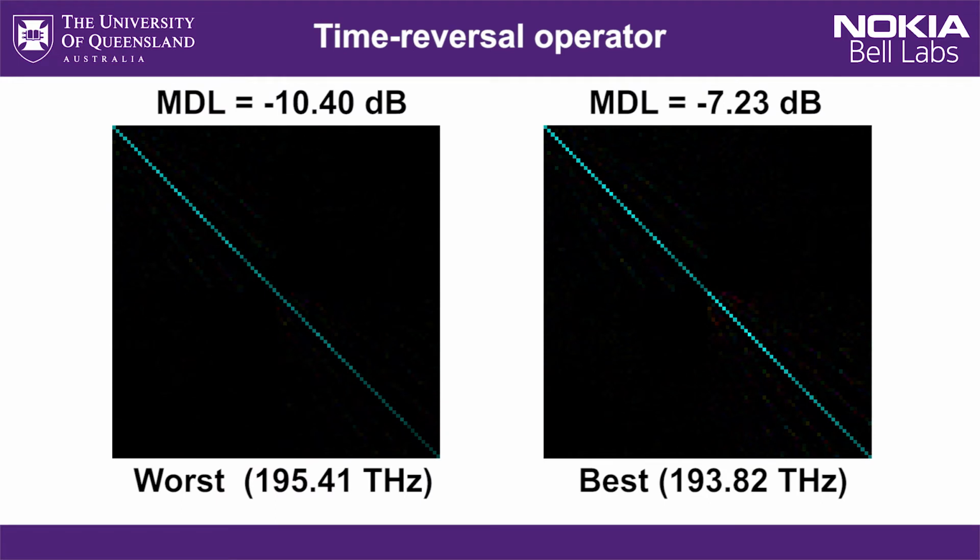reversal operator. This gives you similar kinds of information, measures of how orthogonal the channels are and how much loss they have. So if our device was ideal, we'd have transfer matrices which were unitary, so that is lossless. Or perhaps more realistically, the device might have some overall loss, but it's a loss that's common to all modes, all possible combinations of modes through the device. No mode has more or less loss than any other. They've all just got the same common loss.